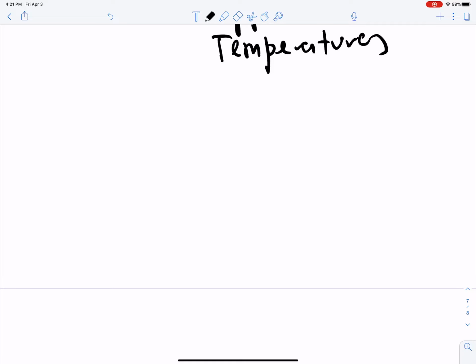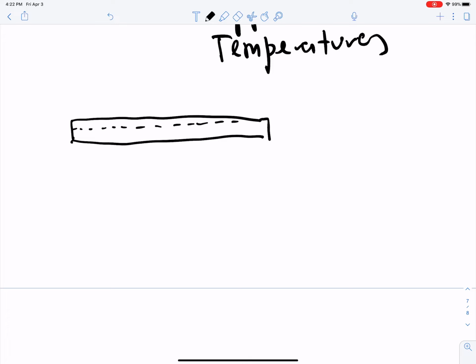So again, what's the idea here? We're going to take our bar, and it could be any cross section. So let's say this is a medial axis. It doesn't have to be halfway between the top and the bottom surfaces. I'm going to put this guy on a pin. I'm going to put this guy on a roller like this.